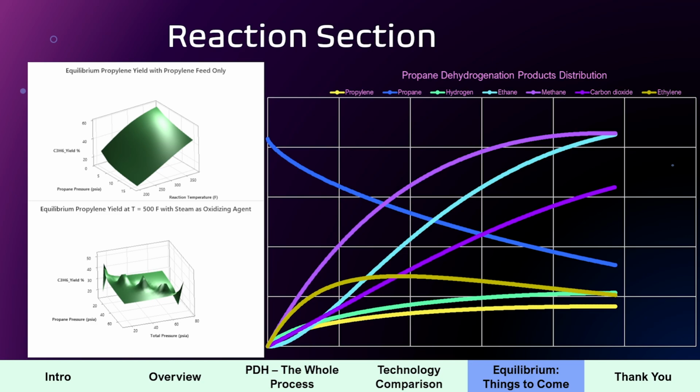So I cannot write a paper about the thermodynamics of PDH and put a chart out there that shows a single reaction, propane to propylene, with my temperature and my pressure, and say that's why we need to operate at high temperature. No, because that chemical equilibrium did not take into perspective the different components that we have.